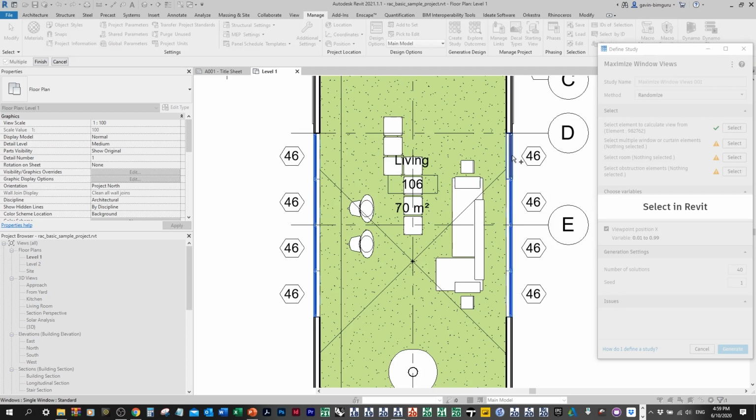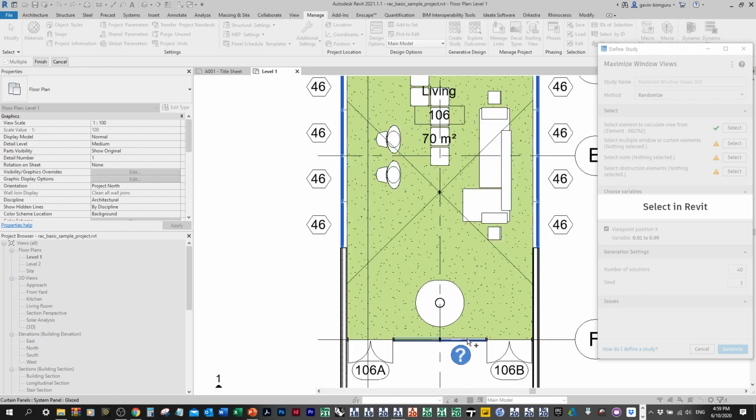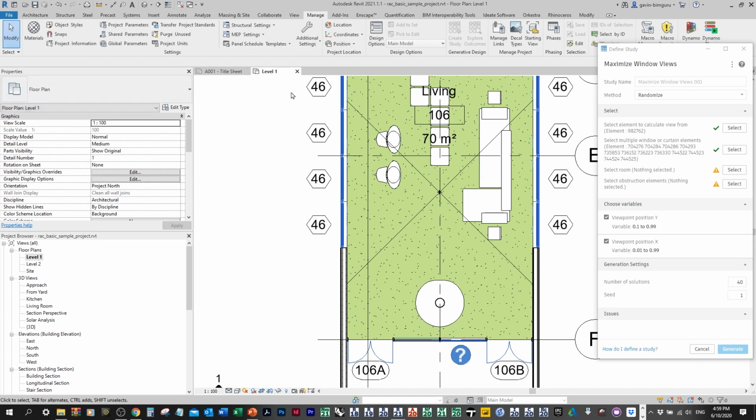window elements. And this is actually using a pretty cool tool from the Generative Design package, which is a filtered selection, which is pretty handy. So it limits how many types of categories you can pick, which is pretty hard with the previous versions of Dynamo, where you have to select any model element you can select. So I find this is a really handy node just in general.